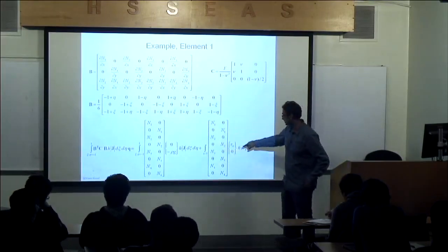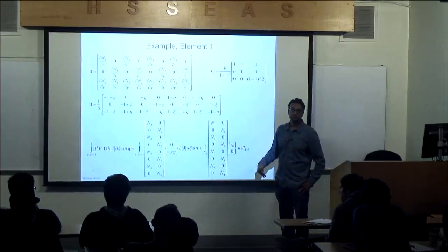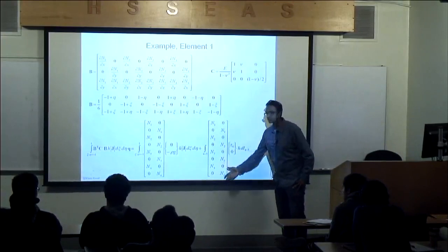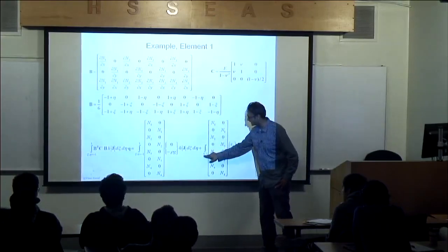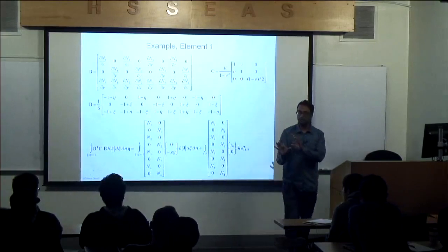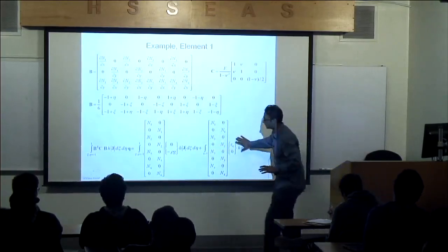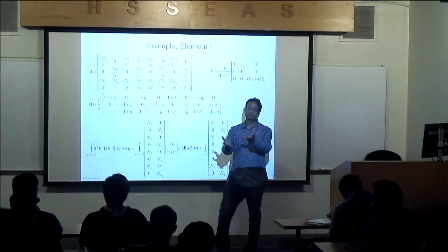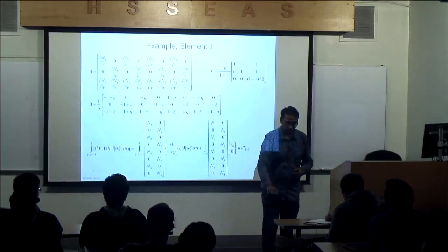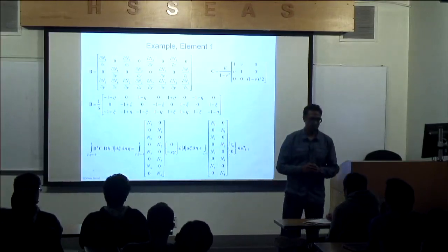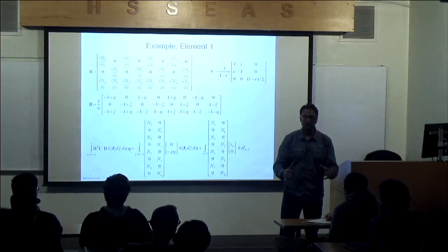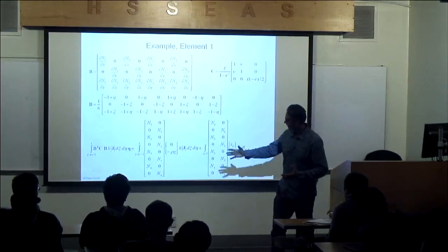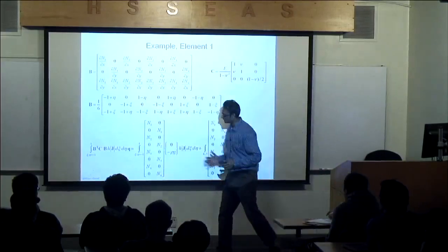So that makes sense, tau 0. There's nothing going downwards. So traction in the y direction is 0. And then again, N transpose. And I have to integrate this now, but in the edge 4, 5. I have to focus on that edge alone. Unlike this one. This one has to be integrated over the area, over the whole thing, because it's the body force. Does the gravity only apply on the surface of a little structure? Gravity applies to the whole body, the volume, all its interior, right? So that's why this looks different from this one. Okay.